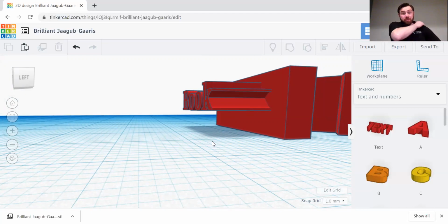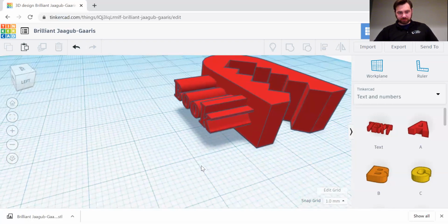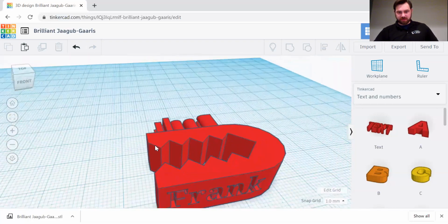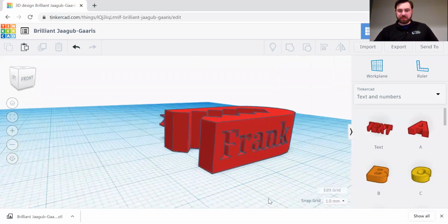If this is a design that you really wanted, when you are importing your STL or OBJ file into the 3D printing slicing software that comes with the 3D printer that you're going to be using, it'll give you the option to put supports up here. So this will print cleanly, and then the supports underneath, you can just snap them off. But that's exactly why I did the indentation. I think it looks cool and it'll print nice and easy.